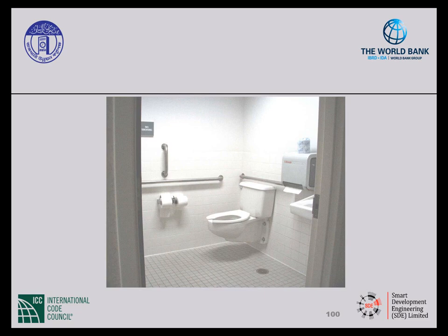I would not locate the paper towel dispenser in that location because it would interfere with someone pulling up alongside of the water closet to make the transfer that we just looked at. And this is missing the fold-up grab bar.